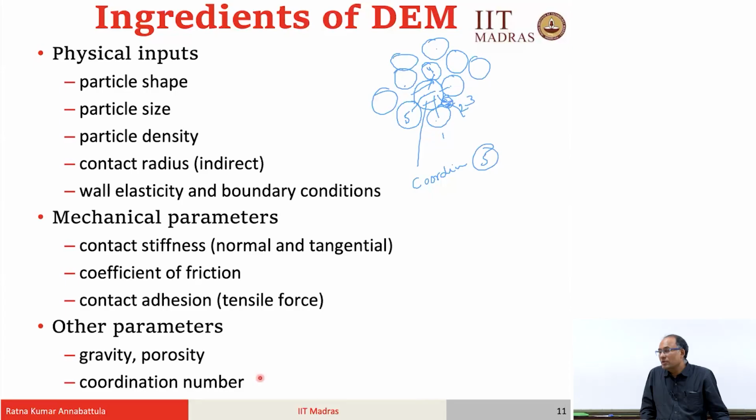because that represents the state of packing. Because you are actually talking about a silo that is confined by your container, and these particles are transferring forces. The force is collectively taken by the particles, and a lot of the force is dissipated in the frictional, tangential force, right. So, each particle effectively may not be experiencing the crushing force, but collectively they are supporting that load. That is why you do not see particle breakage. Otherwise, in silos what should happen is that at the bottom all your particles should be breaking.